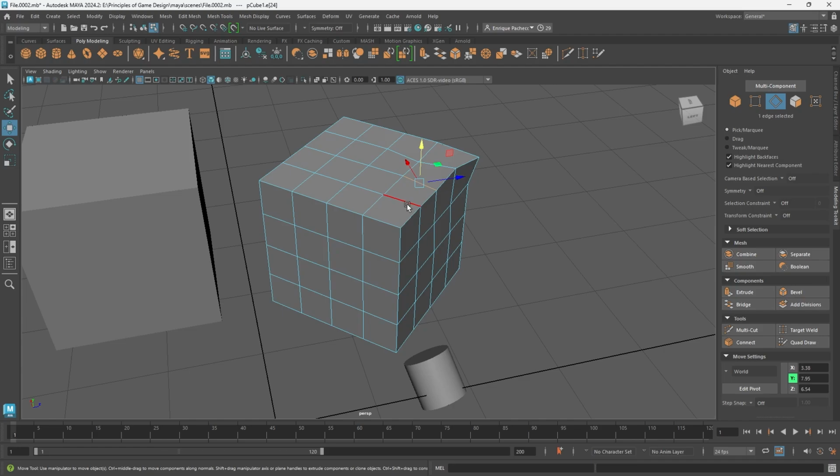If you don't want to select an entire edge loop and instead you want parallel edges, you can simply select one edge and then double-click its neighbor. And that'll give you all of the edge loops that are parallel to each other along the model. So one more time, double-click an edge gives you the edge that it is pointing along. Click one edge and double-click its neighbor gives you a loop going the other way around.